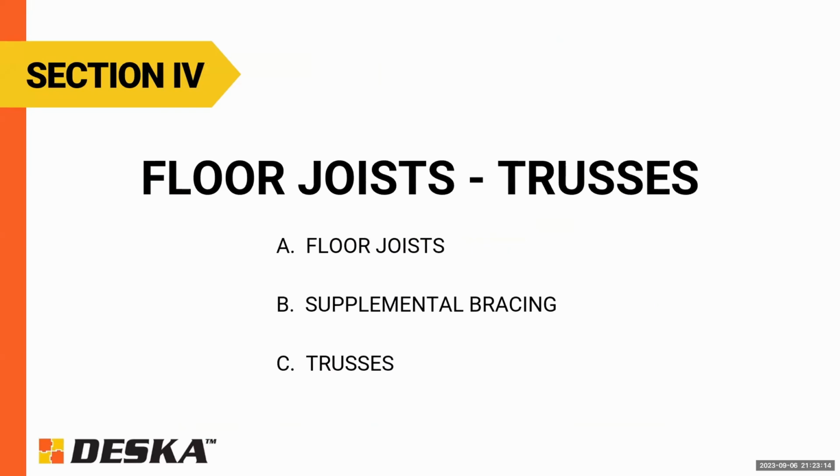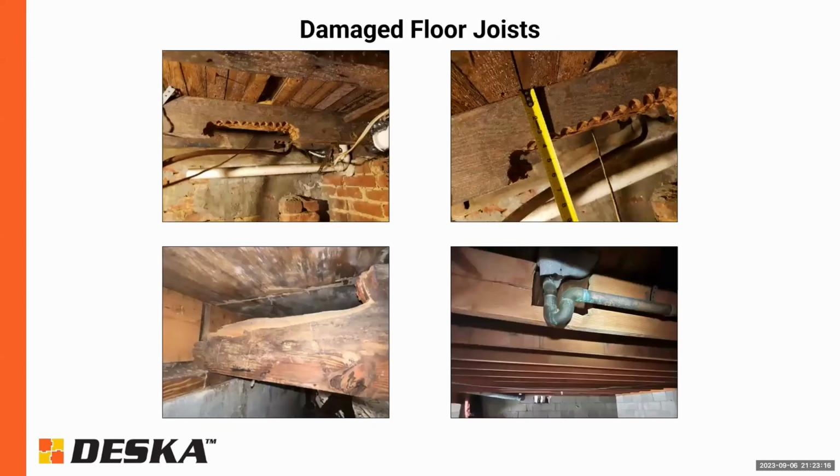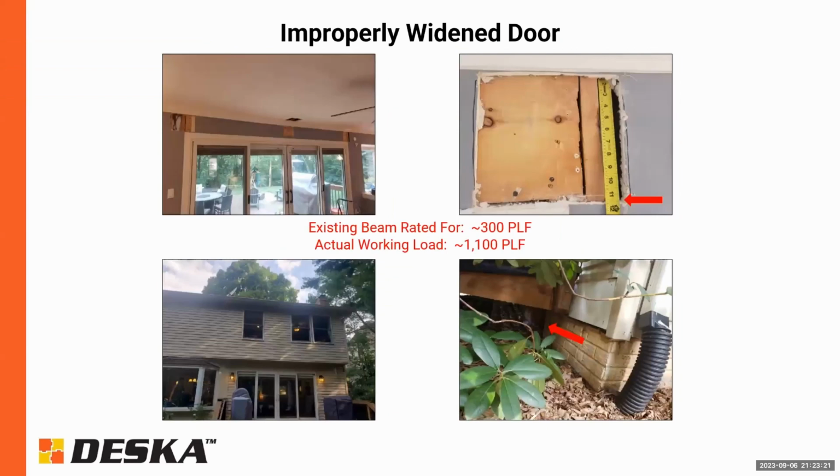Some floor joist issues here. Hey, Brian. Yes. I'm sorry, man. There's a question about that last part. So the new beam supports 1100 PLF, but how much safety margin did you specify? So that's the allowable. So that is the actual. Those are the actual. The factors are included there.